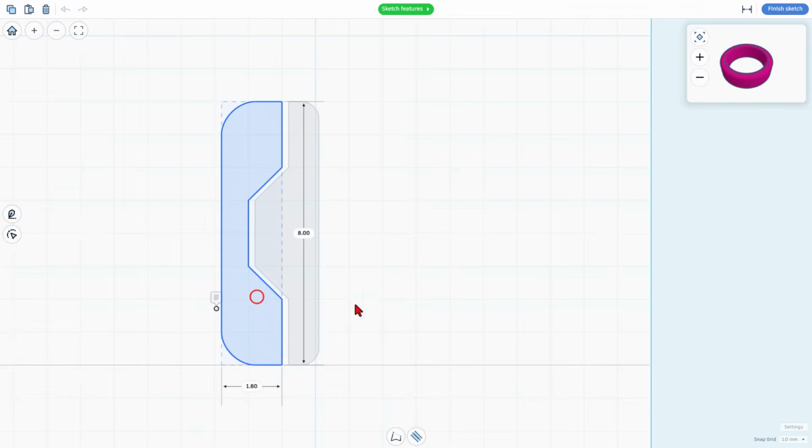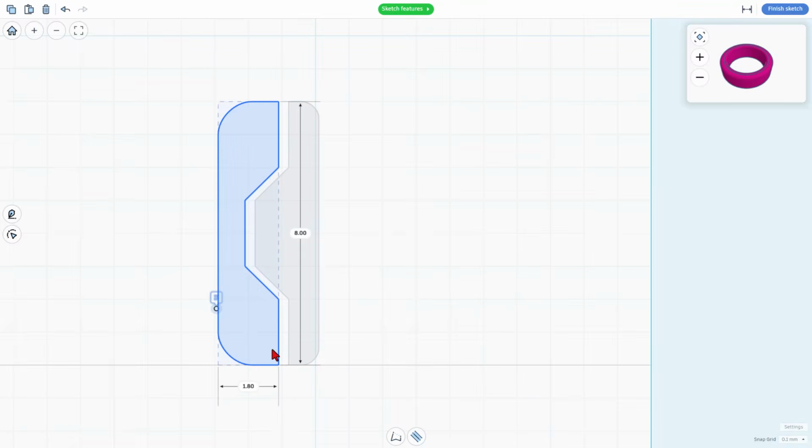Now, while I'm in here, I'm going to mention I had a user say theirs was not coming apart. It was frozen together when they were done. To adjust that, notice I set my grid to off, and this makes it nudge 1/100th of a millimeter. So you can nudge it a few hundredths like I did. Of course, I'm going to put that back. If you want to nudge by tenths, you simply click this. So we used a 0.2 gap between these. If on your printer they are fused together, I would just try a 0.3 gap first, but just keep fiddling as you find the perfect measurements for your 3D printer.